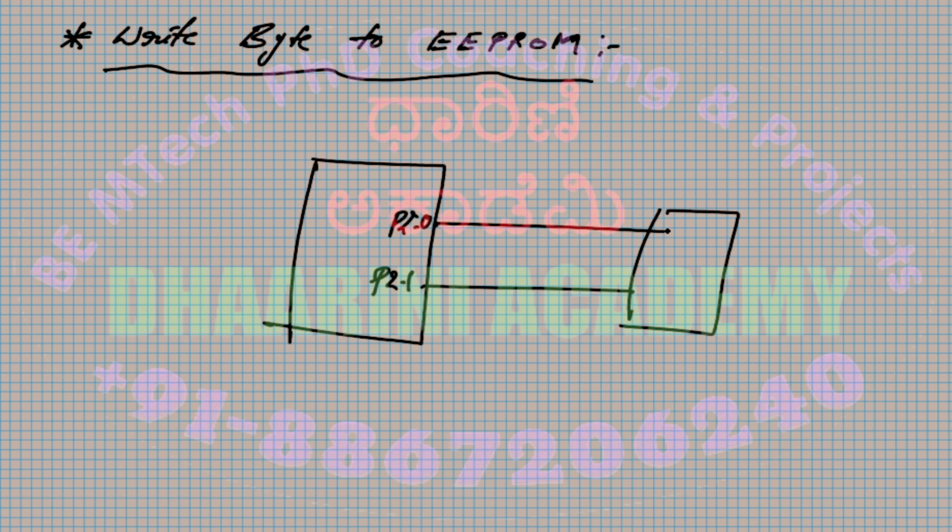They are connected to whatever pin number in your EEPROM is given. I just have to say in my code that if I say P2.0, it is SDA. If it is P2.1, it is SCL. I just have to initialize that in my code.